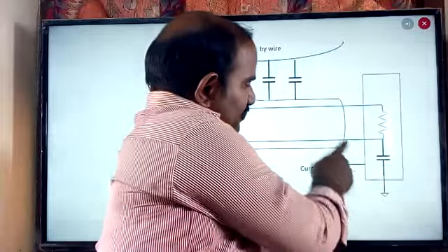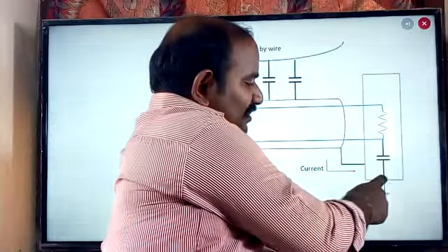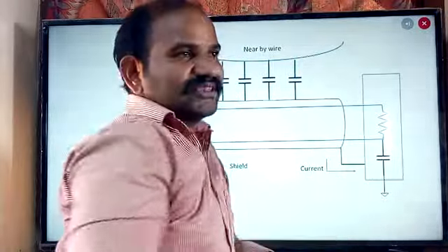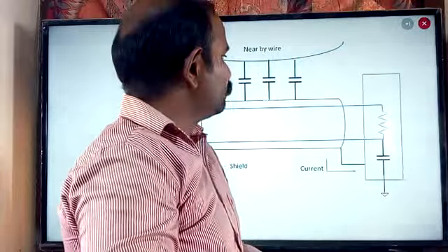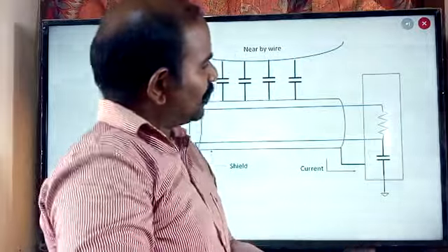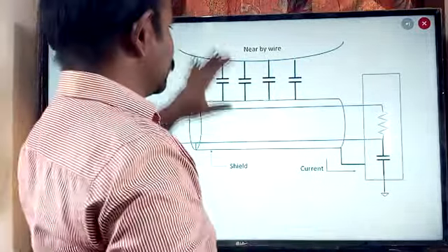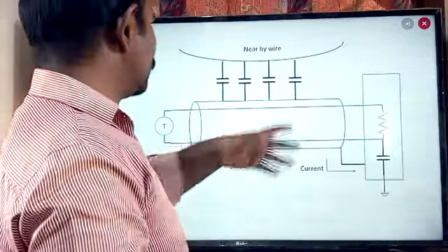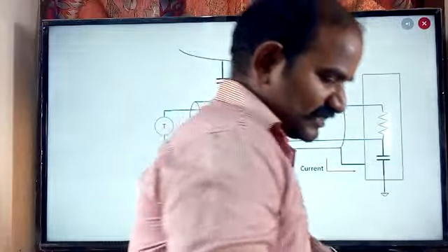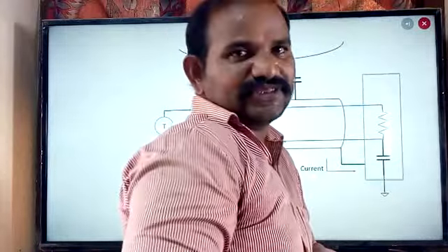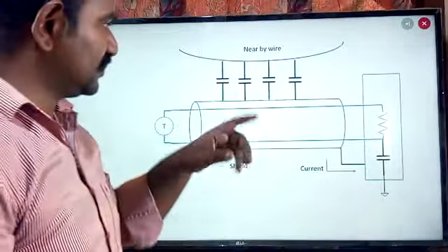So from there, the signal which is coming from here is going to be driven to the ground. We are simply bypassing the noisy signals which are going to be involved when we are placing our measuring system, data acquisition system, under the heavy line wires. To avoid that, we are using the shield. So this is what I would like to recollect from the last class. I thought I missed out those points during the last class, so because of that, I am coming back to this slide.